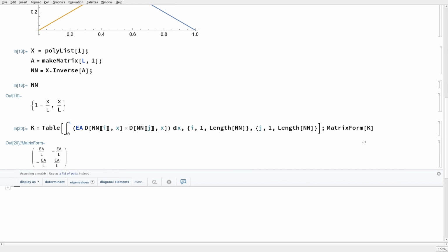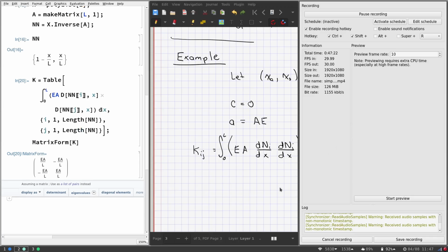This is also known as the stiffness matrix. Even in problems where, say we're solving a mass balance equation, we still call it a stiffness matrix. And it's just legacy. Originally finite elements was formulated in a matrix methods and structural mechanics way. And so the stiffness matrix meant the stiffness of the system, right? But we still call it that even if we're solving a different problem. But that's our stiffness matrix. So let's just briefly go back to our notes.